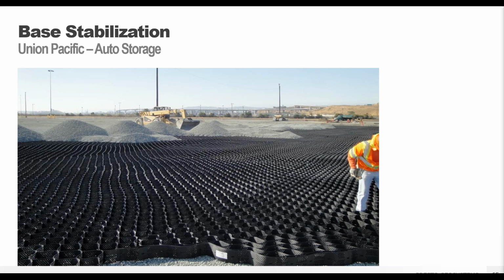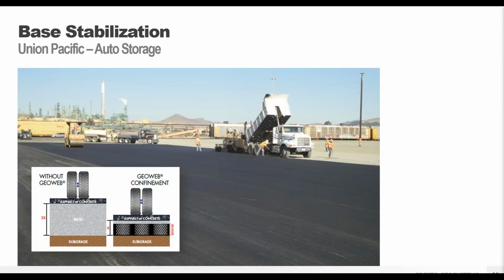And then placing the panels is really quick work, almost always faster than actually infilling those panels. So it's not really a concern to have the stone catch up to the workers. Usually those workers are going to go a lot faster. Typically, we say a crew of 4, so 4 laborers plus 1 operator, will get in around 1,000 square feet of material in about an hour. So that gives you a base starting point of how installation would go.